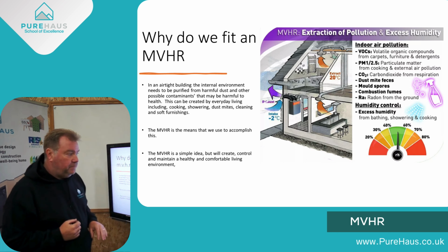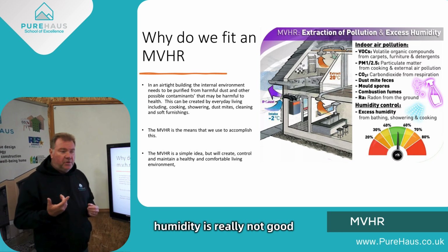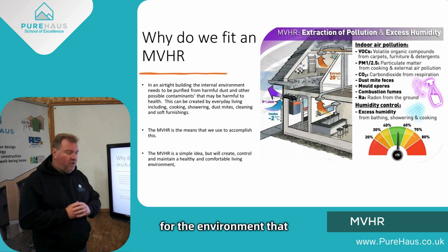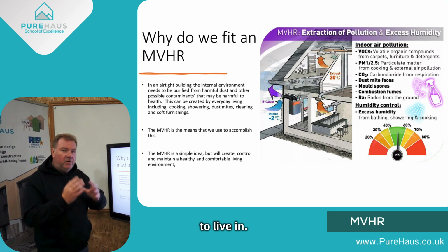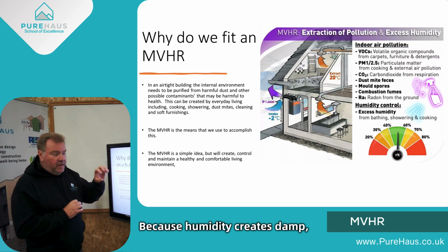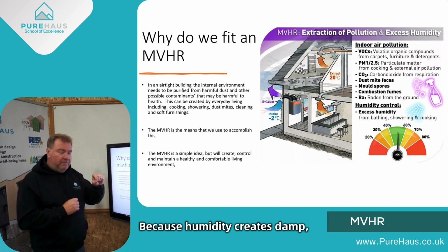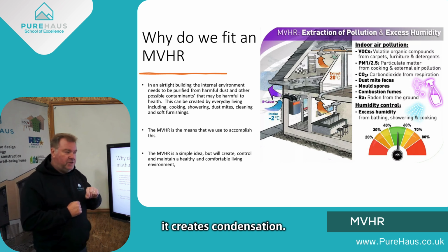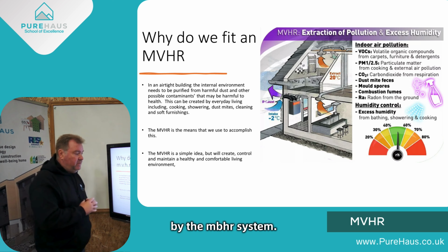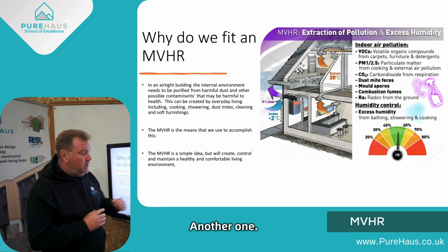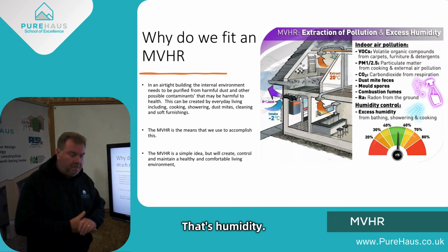Humidity control. Too much humidity is really not good for the environment that you're going to live in, especially when you've got an airtight envelope to live in, because humidity creates damp, it creates condensation. It's something that we really want not to have to deal with. So it's dealt with by the MVHR system.